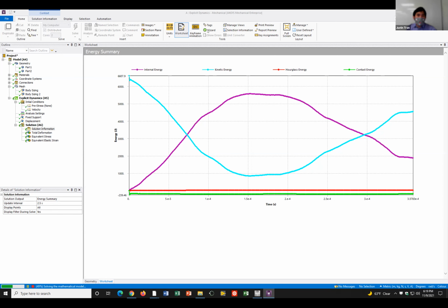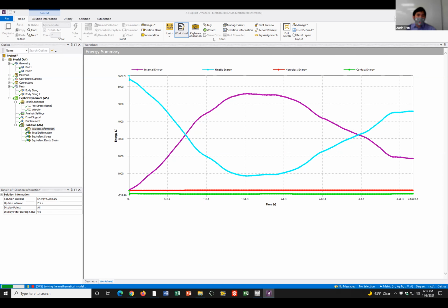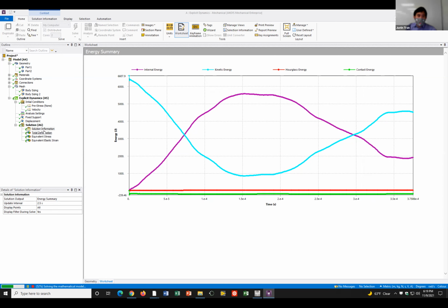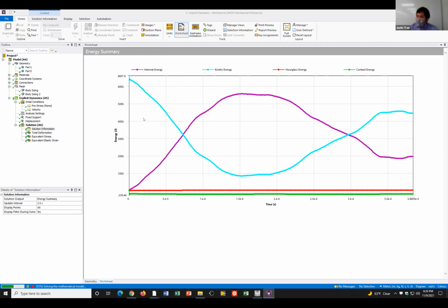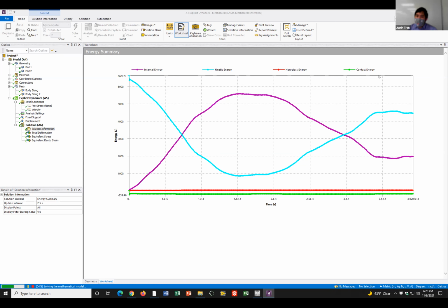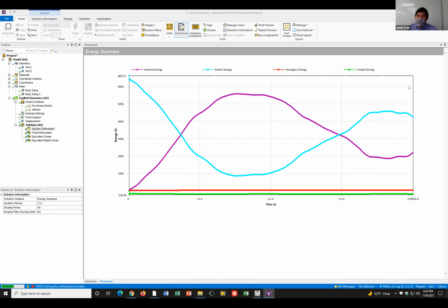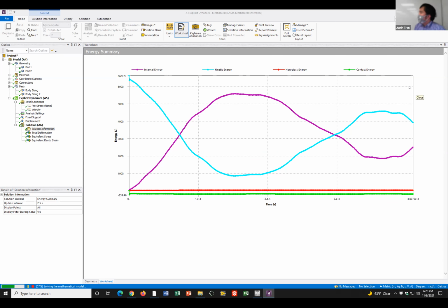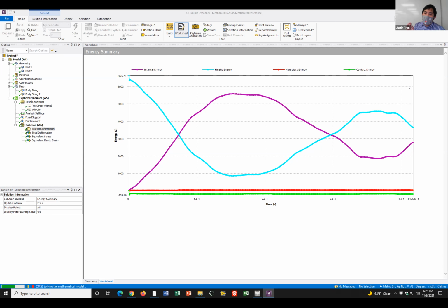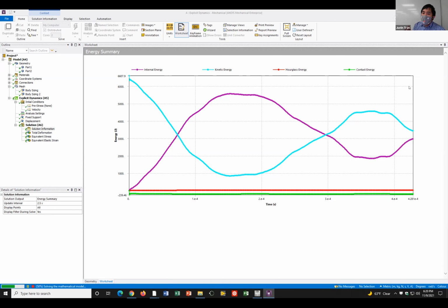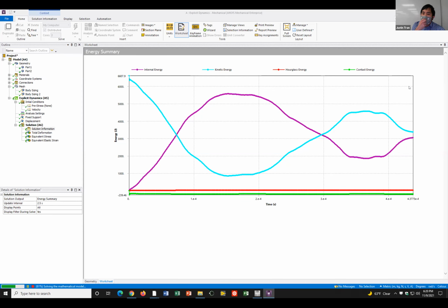Yeah, basically, and I'll speak now, in case people have to run, the total deformation field in this one is a little bit deceiving, because it might give you the sense that it's deforming a lot more than it is. The reason for that is the way deformation is computed: it takes the initial position of where the mesh element was, and then subtracts it from the final position.